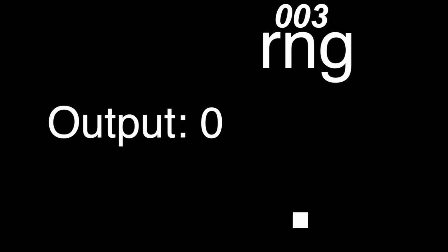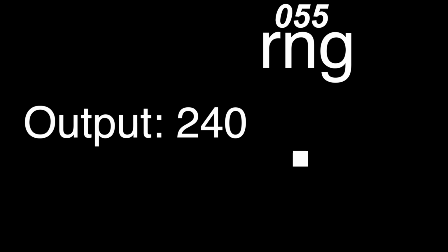I have not yet ordered all the parts for the 8-bit computer, and so I will be testing these modules in their 4-bit form, but the logic is still the same, just fewer wires and chips. The new module also has a buffer register at the output, so once a random number is picked, it will stay there until a new one is picked, to avoid having issues in the future with timing.